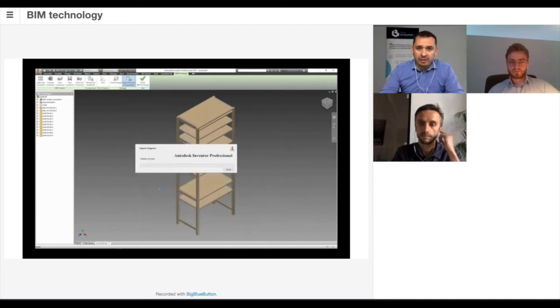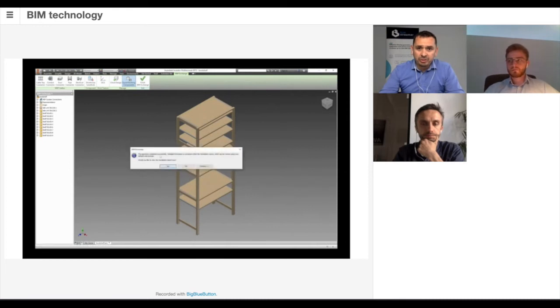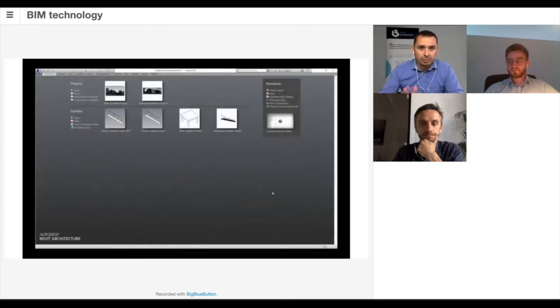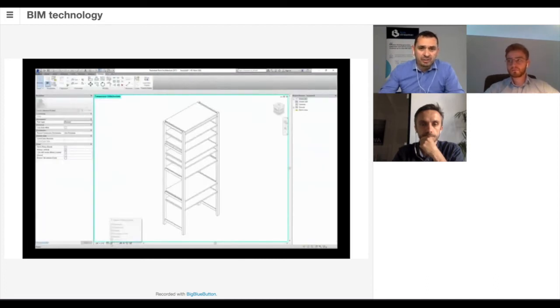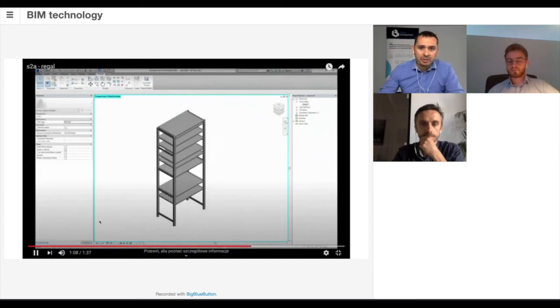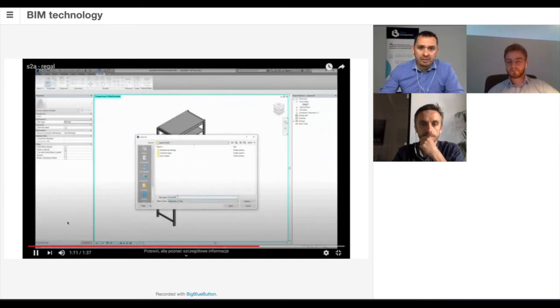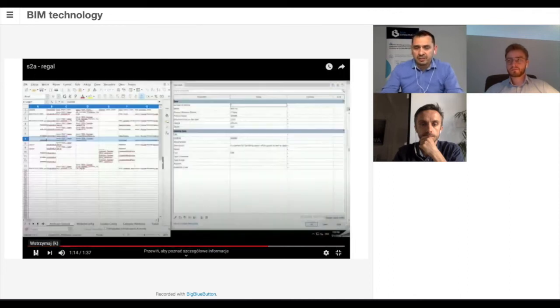And right now we're storing the model, the Inventor model. Here you see the confirmation that everything worked, and there was a question whether I would like to see the conversion report, so let's skip that part. We're opening Revit, and as you can see within Revit, we've managed to open the ADSK file, and at the very end, we save that as a Revit family.